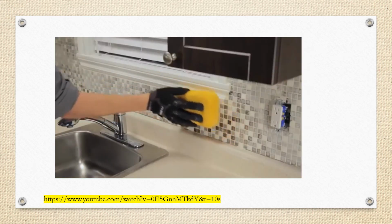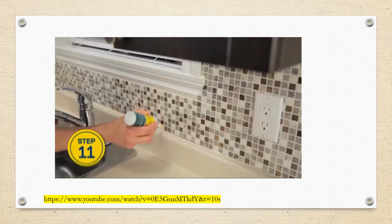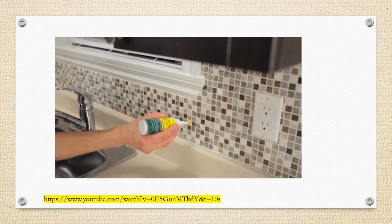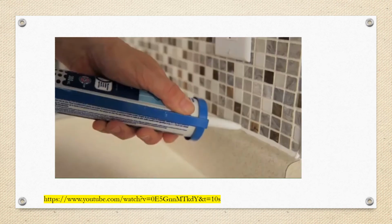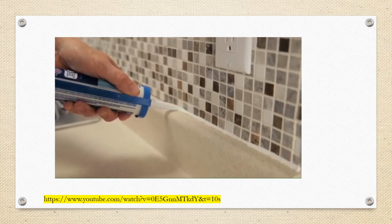Rinse the sponge often, using as little water as possible so as not to dilute the grout. After 24 hours, when the grout is completely dry, apply grout sealer to the joints. Finally, after about 10 days, caulk the expansion joints with silicone sealer.